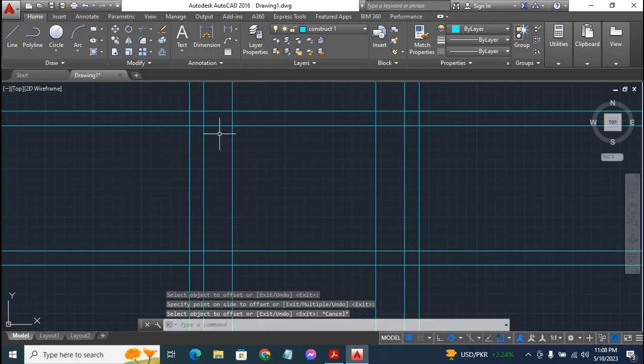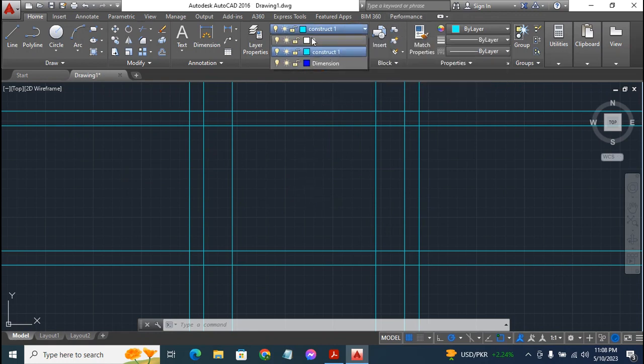Done that. All right, so this shape right here is where we are going to be having our smaller rectangular shape here on both ends. So quickly, I'm going to go back to our main layer. Go to layers, click on the drop down menu of the layers toolbar, then select the 0 layer, click on it to select it. Now we are in our main layer.